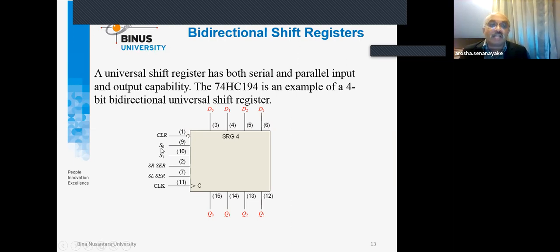So these are called S, which means select. So select signals, select pins. Based on the selection, we have two, S0 and S1. That means how many combinations do we have? We have 2 pins, meaning 2 bits, so 4 different combinations. Based upon that, the circuit is really controlled. Yes, that's very important. So the chip is controlled.